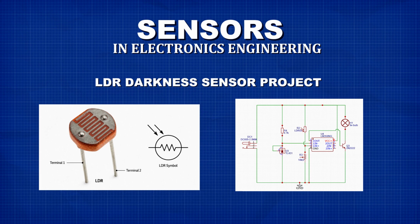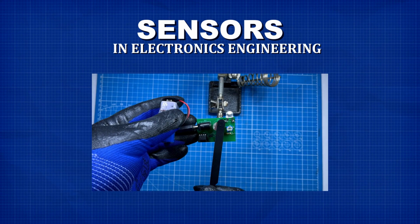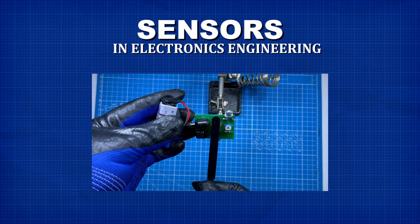In this circuit, the LM358 works like a comparator. It compares the LDR voltage with a reference voltage. When the environment is bright, the lamp stays off. But when the environment becomes dark, the LM358 detects the voltage change and activates the transistor. The transistor then works like a switch and turns on the lamp automatically. So the LDR senses the light. The LM358 processes the signal. The transistor switches the load and the lamp responds.